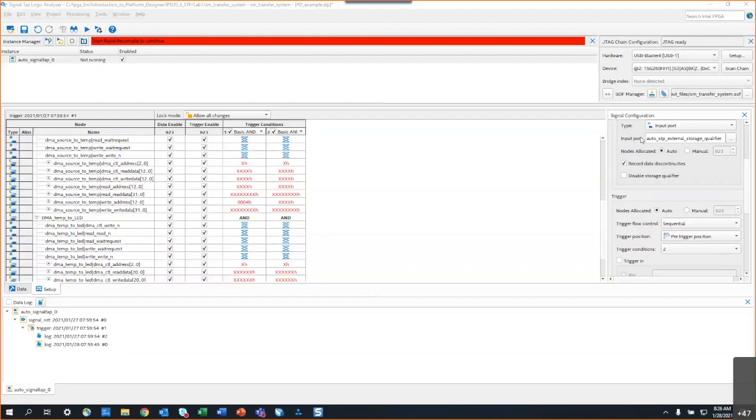Gosh, that could end up being a timing issue again. When I'm observing 4 signals, the result is correct, but add more signals for observation, there are errors. That's a tricky one. If it was working fine with 4, and then you're adding more to look at in Signal Tap, and now things are not working correctly, that could be another timing issue, like what I was speaking about earlier.